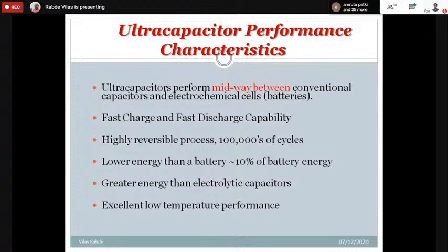You know, our conventional battery, that is the lead acid battery used in your scooter or motorcycle, can withstand only 500 cycles and then it degrades. And if you remember, a few years back there was a wave of electric vehicles in Pune, and most of the companies stopped only because of the battery quality, because though they were claiming 500 charge-discharge cycles, they were really deteriorating around 300 cycles.